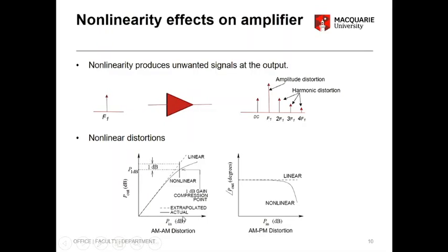So this is your input power, this is your output power. For the given input, you have an output power level, right? So that means this gradient will give you your gain, right? P out over P in, right? But this is in dBm, so it won't give you a gain. Okay, so in this case it won't.